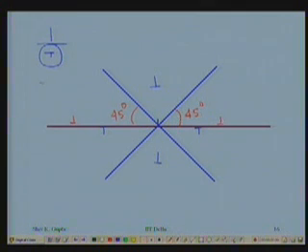When I have a dislocation just below this, of the same sign, I have compressive strains here. So there is a region here where positive strain and negative strain meet each other and cancel. So there is a volume of the crystal where strain energy is not stored. So the energy of the crystal is lowered by this. So here same sign attract, and here opposite sign attract.